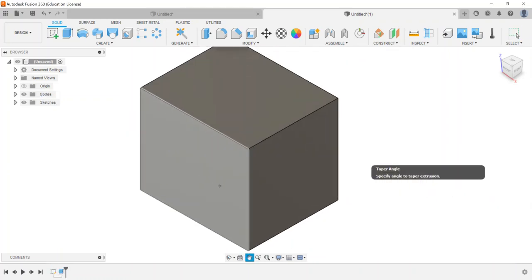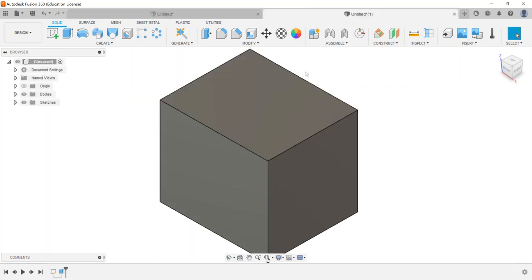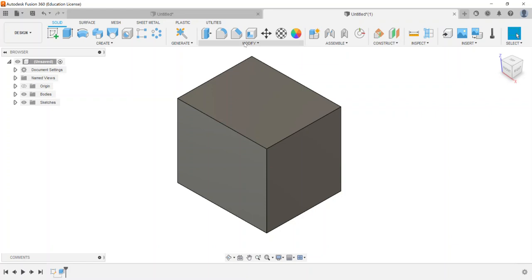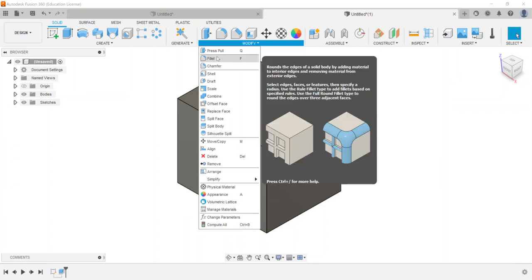Now, in this last shape, we had a rounded fillet here, we had a chamfer here, and we had a chamfer up there. So what I'm going to do is, in the part modeling aspect, you also have, in the modify panel, a fillet and a chamfer. The good benefit of utilizing these is it's easy to go back and edit them. As opposed to the sketch environment, where you have to go back, and there can be some interesting scenarios that happen with those constraints.